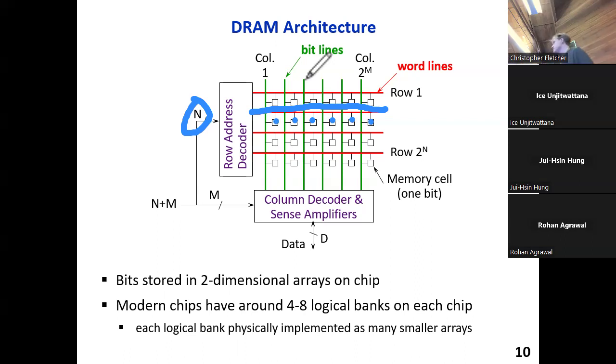It's just the address bits. So you have some number of address bits, n plus m. So imagine just an address that your program can understand. And what's interesting about DRAM and any memory technology is once you hand your address to the DRAM, it can decide how to use different subsets of those address bits in one of a number of ways.